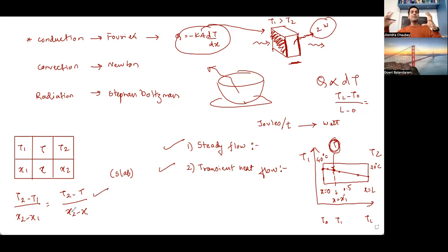When the material is the same throughout, then comes the topic of series and parallel. What is series? Series kind of numericals come wherein one slab is attached to another slab and the materials of both slabs are different. So the K changes. The K for material 1 would be K1, whereas K for material 2 would be K2. In that case, you apply the series relation.